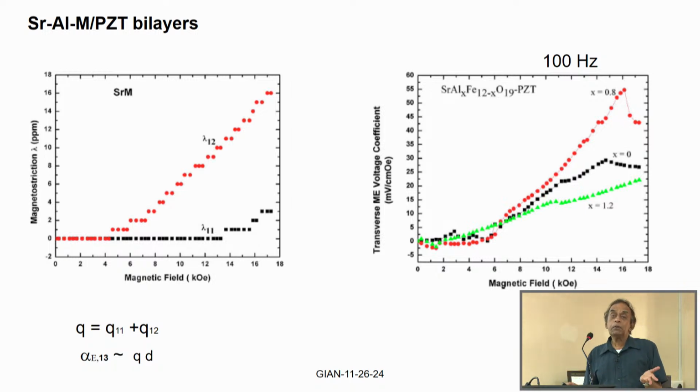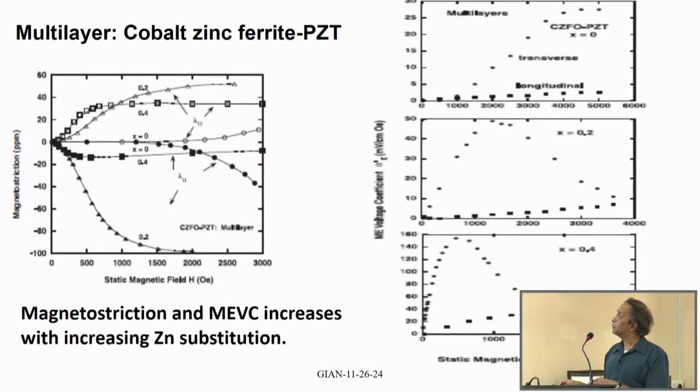So, if you want to put together a sensor of DC magnetic field, then you want to use something like hexaferrite, because with nickel ferrite or nickel zinc or 3D transition metals, if you look carefully at the magnetoelectric response, I want to show you quickly.